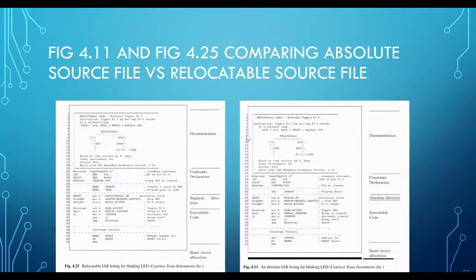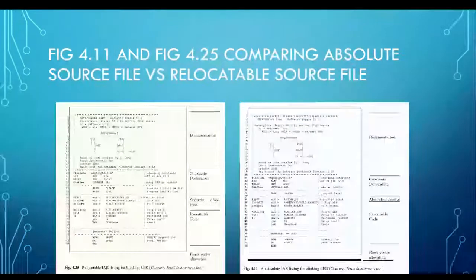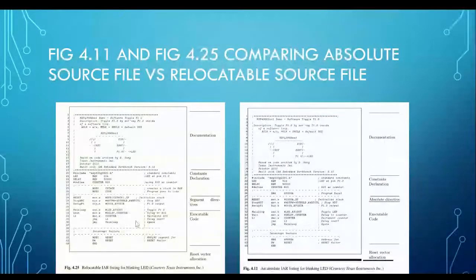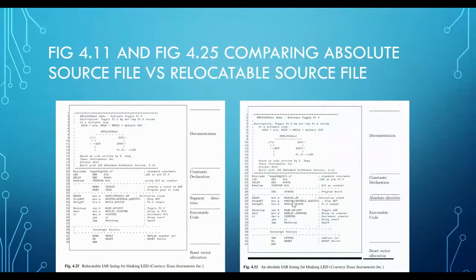So you can see that we always assign the interrupt vectors. We can have several interrupt vectors, for example this part. We assign this address as the reset vector, and we also have to assign addresses if you want to use timer modules and so on. You always have this address unless you use the automated method. Else you need to define where the address is and so on. If anything happens, you will go to reset, etc.